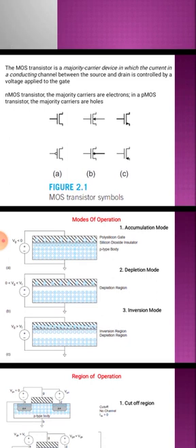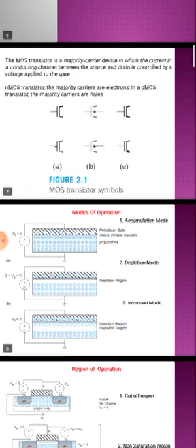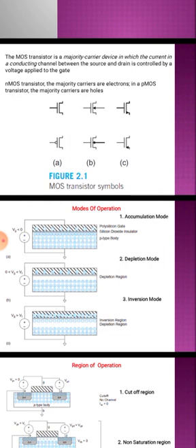gate insulation. But in depletion mode MOSFET, the channel is by default present between source and drain terminal during the manufacturing process itself. That is called by implant. The purpose of applying voltage at the gate terminal in the depletion mode MOSFET is to increase the conductivity. So the basic difference is the channel that exists or evolves between source and drain terminal.